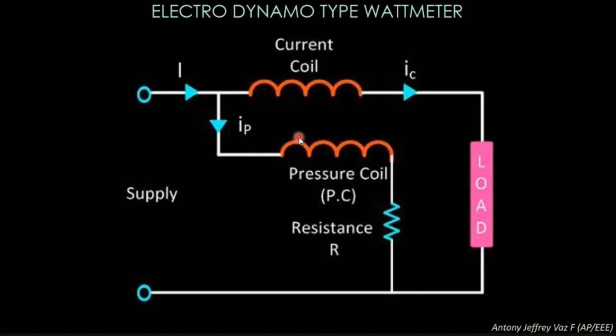To measure how much power the fan consumes, you need a wattmeter, and it will show how many watts, 10, 20, 40 or 60, the fan is consuming. Normally the ceiling fans in our homes consume 40 to 50 watts. Some very old fans will consume about 60 watts.